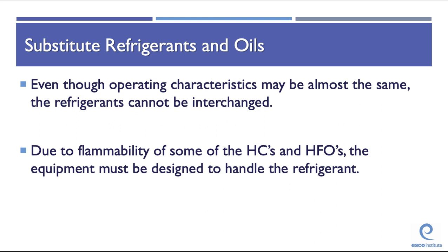Even though the pressure-temperature relationship and the operating characteristics may almost be the same, refrigerants cannot be interchanged due to the flammability of some of the HC and HFOs. The equipment must be designed to handle the refrigerant. Therefore, EPA regulates the maximum amount of refrigerant that can be used in the new systems by their type and use.